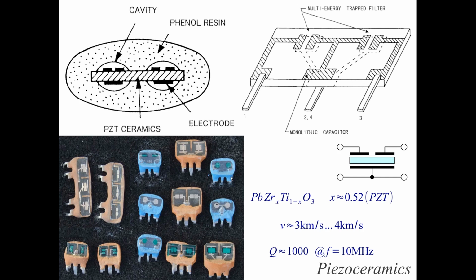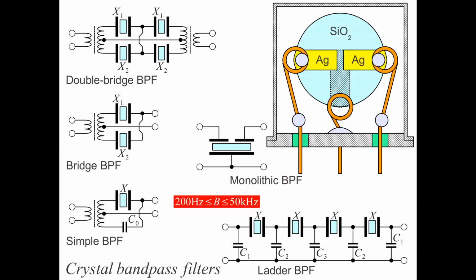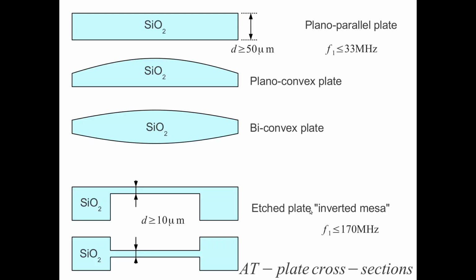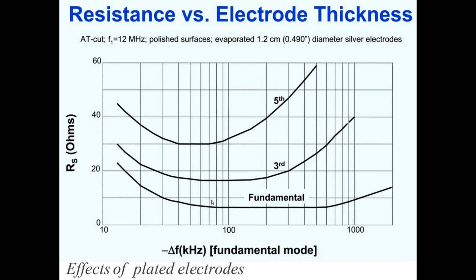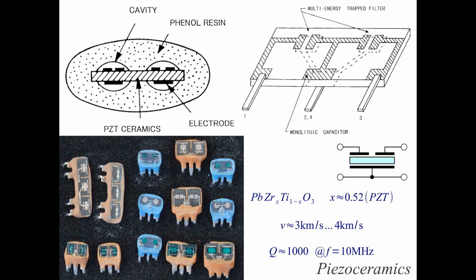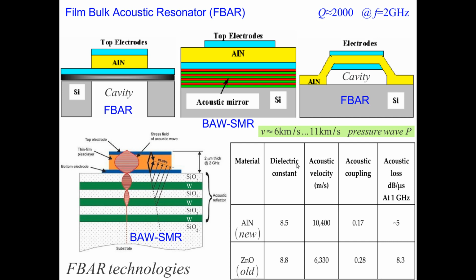So in the case of analog communications, these filters were quite useful. They are not of that much use today. But still, we would need something else in our communications, not just quartz, because quartz is also limited. Its fundamental resonance is limited by the plate thickness. We cannot do everything out of a simple quartz plate, though they form the best possible resonators. But sometimes we would need something else. And that something else can be done with ceramic for relatively low frequencies, below 30 megahertz.